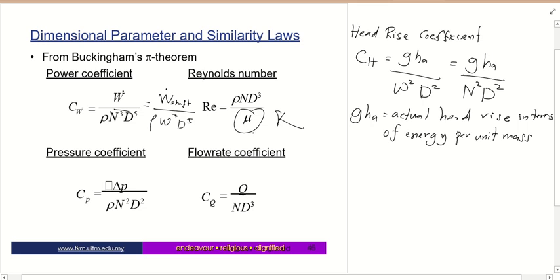When the pump flow involves a high Reynolds number, as usual for engineering cases, experience has shown that the effect of the Reynolds number can be neglected. Okay, for simplicity, the relative roughness, epsilon over D, can also be neglected in a pump, since the highly irregular shape of the pump chamber is usually the dominant geometric factor, rather than the surface roughness.